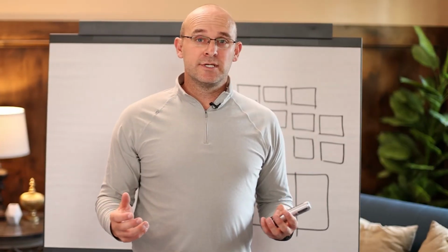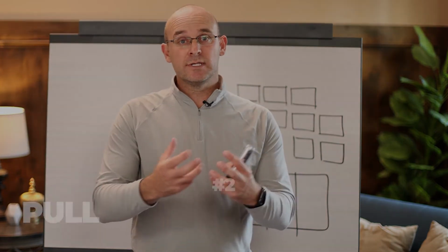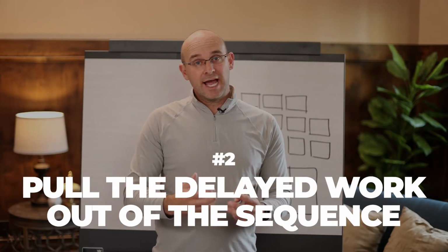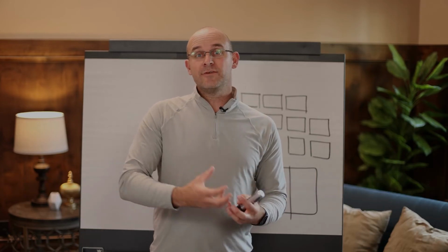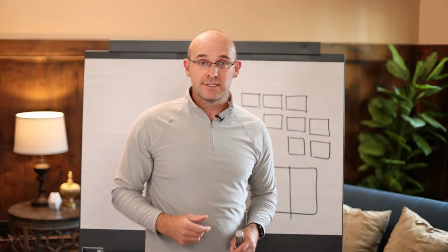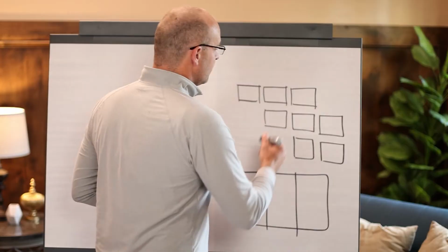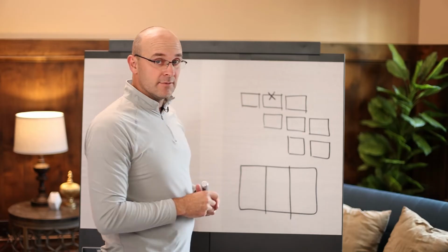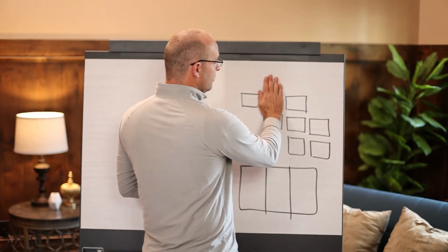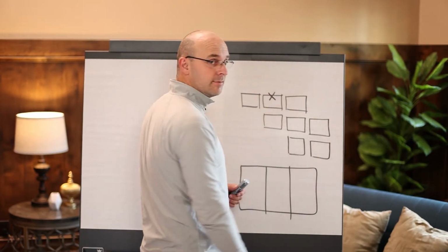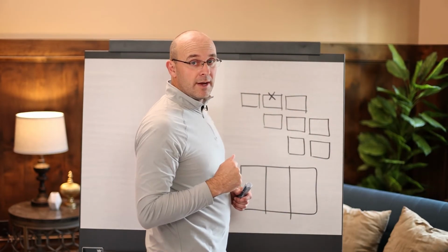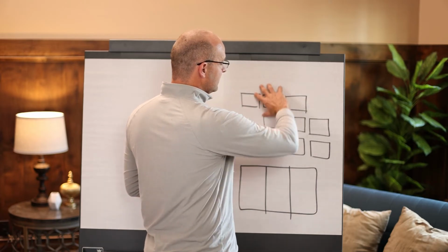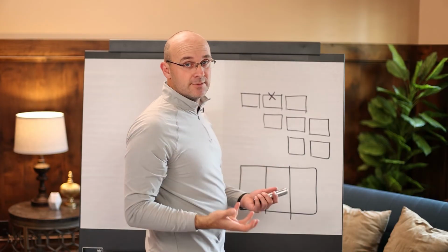The second approach to dealing with the delay is to pull the delayed work out of the train, or what most people would understand is out of the sequence, or even out of the map from a zone standpoint. So let me show you what I'm talking about. So if you experienced a delay here with this activity, in the previous video we said, hey, you can move this, maintain your line of balance, right? And go work on backlog, or stop, wait, and prepare, or try and resequence these and shift them around so that you can absorb that delay.